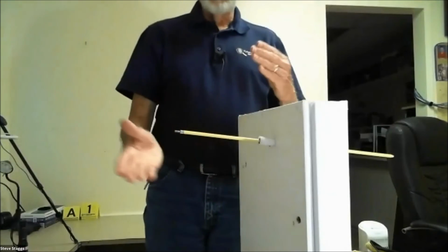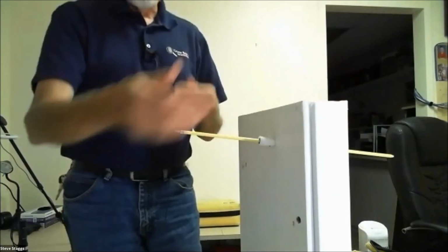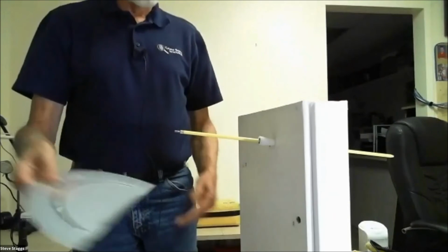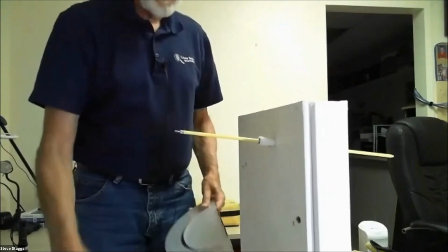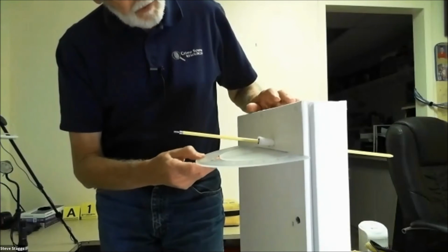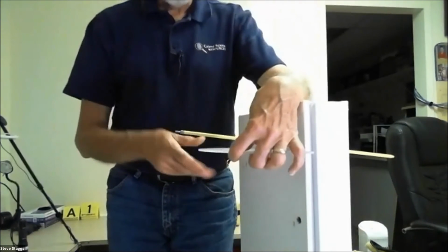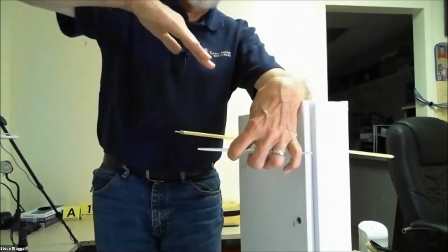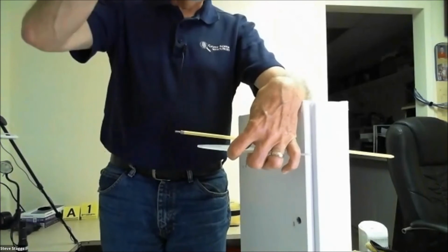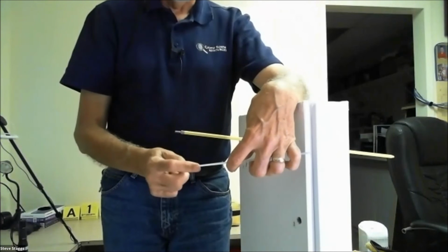But we need the vertical angle, but also we need the horizontal angle. So even if you had this, you're going to use it for the horizontal. You have to position this right under the rod and look down. Now, if it's at a steeper angle, what you want to do is use your plumb bob to find out what angle is reading here.